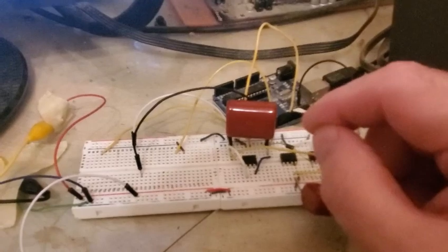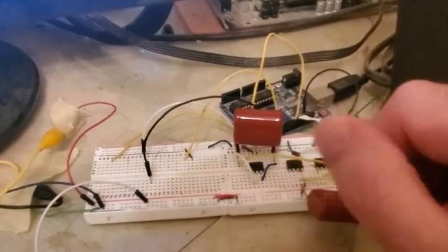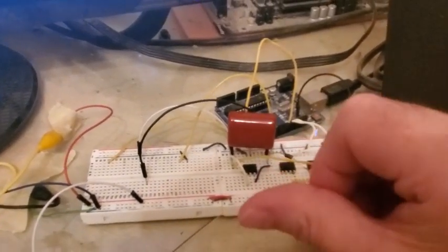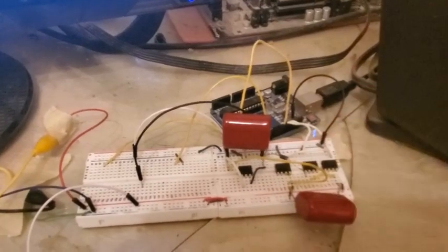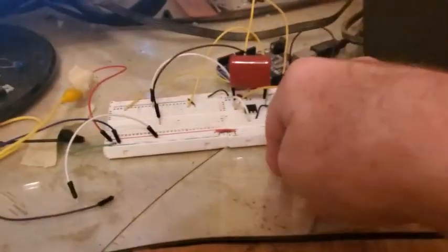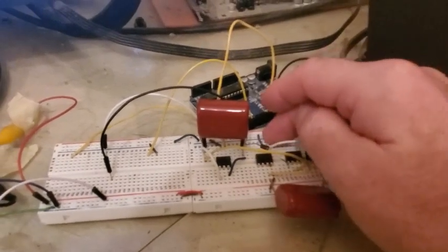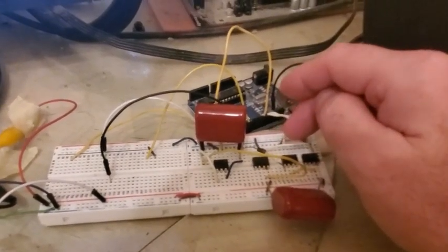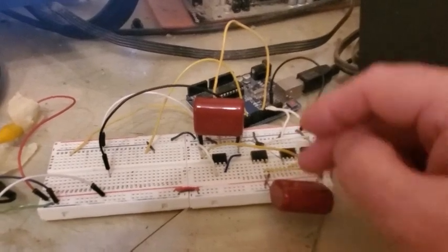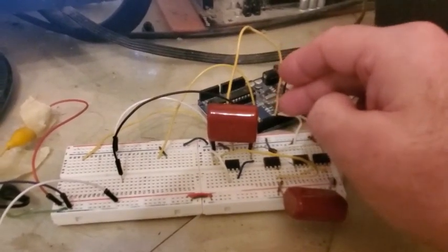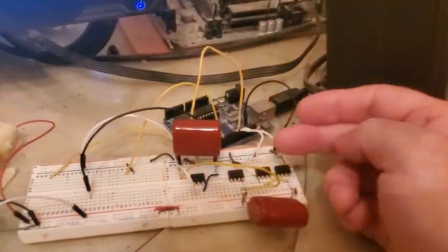One of the next projects that I'll try to do will be how to trigger a MOSFET with an opto isolator. One other point: if you just have a MOSFET off of your Arduino, it's not going to work. Somehow it leaks back into the Arduino ground, and so you never see this oscillation. So you need it opto isolated.